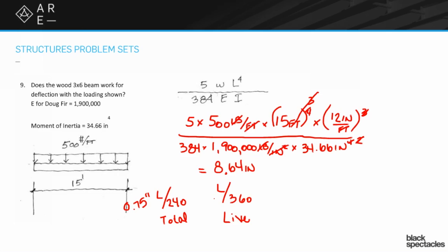But then there are some very specific situations where you could imagine a question where it's much more highly tolerant, because there's a very particular need, like the masonry or something. But the vast majority of them are going to be either this L over 240 for the total load or L over 360 for the live load. Correct. Yep. So knowing that we have so much deflection, the easiest way to change that is to figure out what's in that denominator and make those bigger.